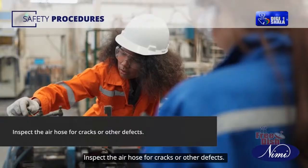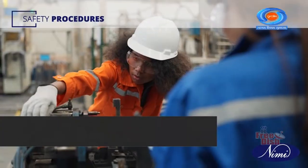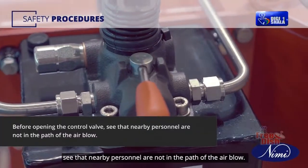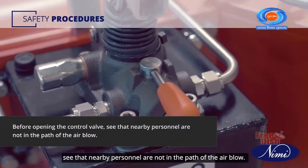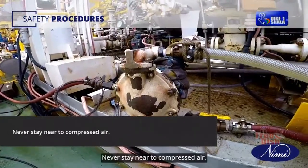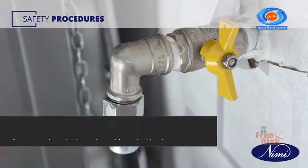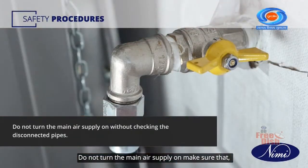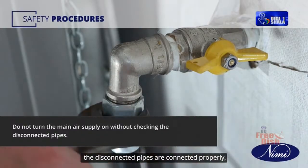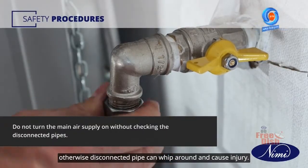Inspect the air hose for cracks or other defects. Before opening the control valve, see that nearby personnel are not in the path of the air blow. Never stay near compressed air. Do not turn on the main air supply until you make sure that the disconnected pipes are connected properly. Otherwise, a disconnected pipe can whip around and cause injury.